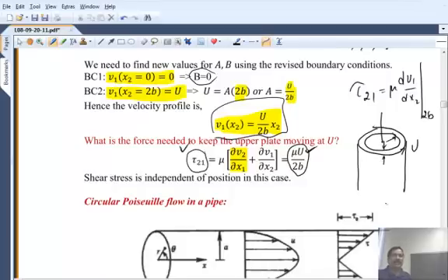That a thin film of fluid between the sheet that he drops and the table, there is a thin film of air, okay, that acts as a lubrication, so that the sheet will glide along the table for a very long time. But if you punch a few holes in it, the air escapes from there. Then the sheet makes contact and friction takes over and it doesn't move as much.